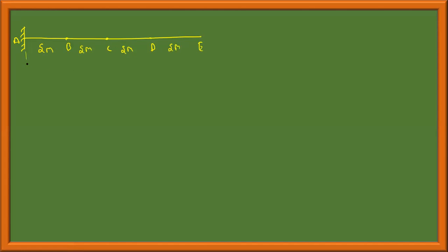Cantilever, in the sense, you should have a reaction force and a counterclockwise moment. Whereas in case of a simply supported beam, there is no moment. It will not withstand the moment. It will simply fall off. In a cantilever, there is a reaction force Ra and moment Ma.